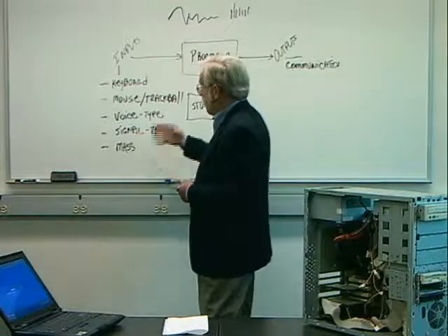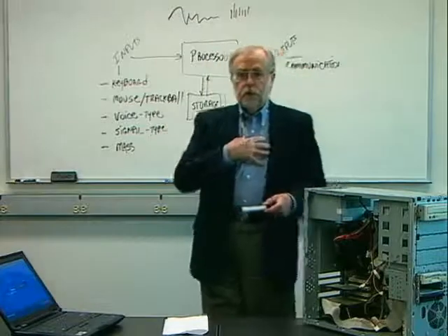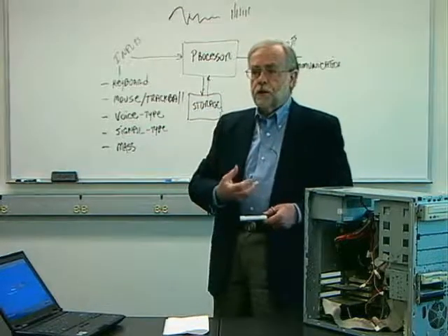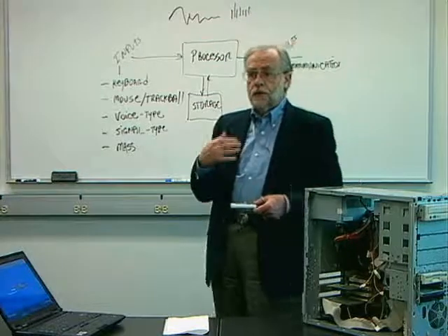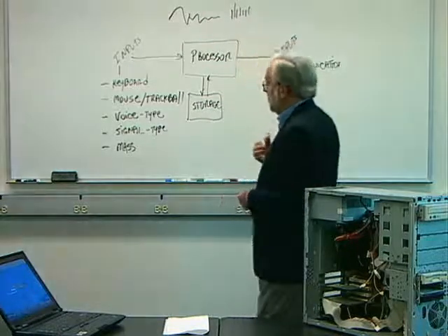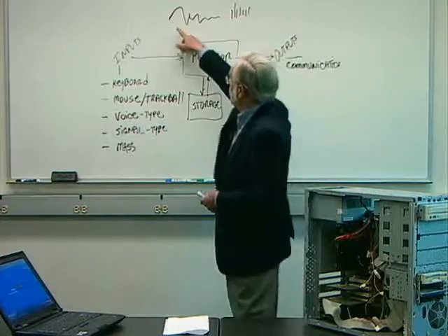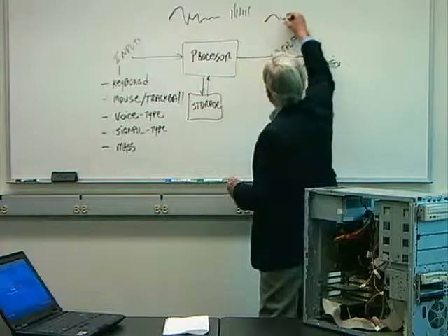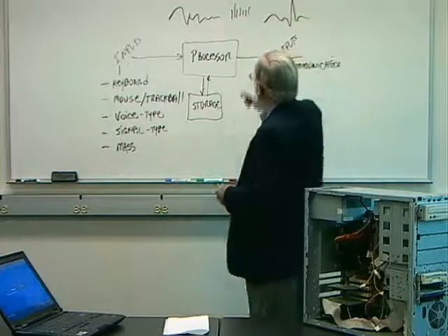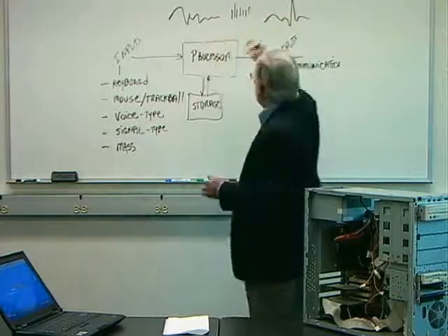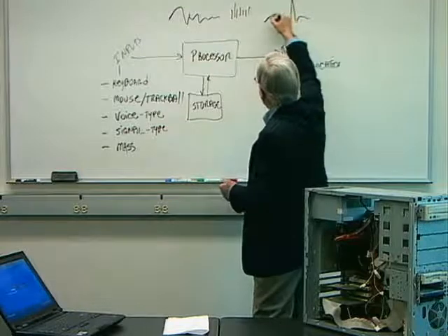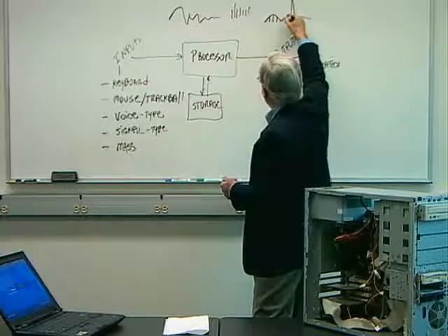Signal type, I could, for example, put leads on your chest and bring your electrocardiographic information in the same way I can bring the voice in. It looks like a signal sort of like this, and I simply turn that, by a process called digital sampling, into a series of numbers that indicate the height of the waveform at each point.